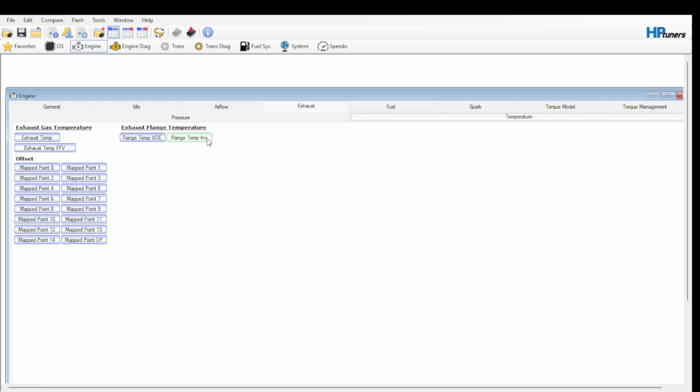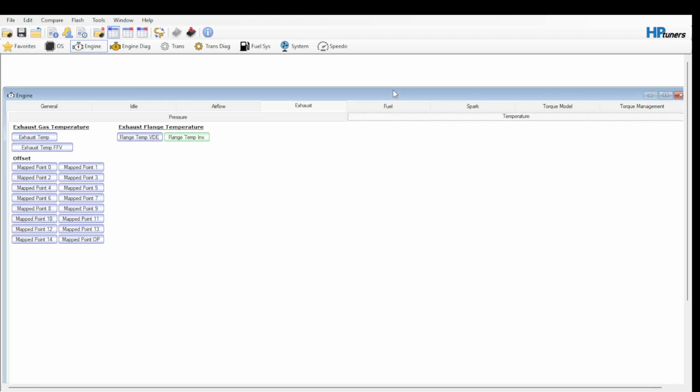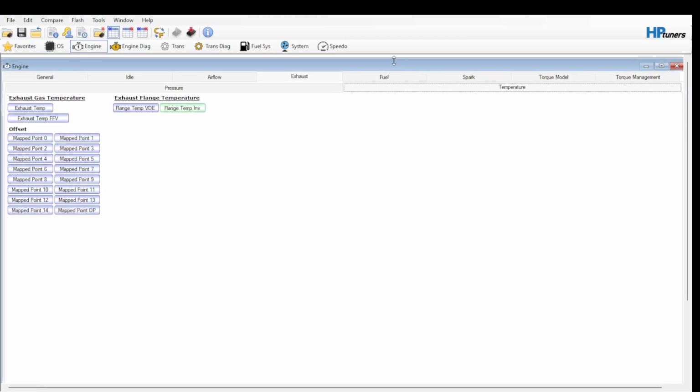Just a couple things you've got to know, like the bolts that hold the triangle of the 3 big T47, or whatever it is, the bolts that hold the turbo housing to the manifold, are not reusable, right? You have to read these things. They have them in the manual sometimes, and then sometimes online forums are actually helpful. And then you should be able to tell, now this is a nuanced thing, but these bolts are interference fit, so they're designed to interfere, if you will.